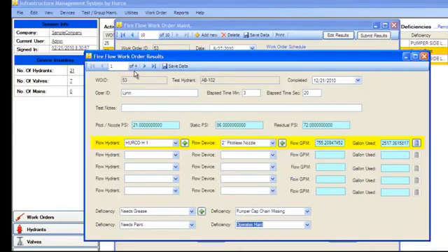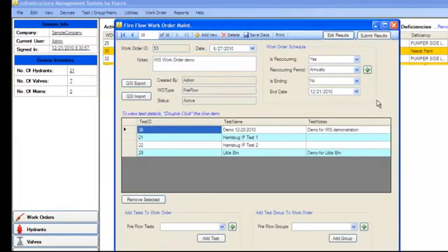And then I move on to the next hydrant, and the way I do that is to click on the little arrow, and now I'm on hydrant 2, and I can go in and enter that data as well. Again, if we had imported or synced with our FireFlow Pro system, all of this information would be filled in right now. So I'm not going to go ahead and do the other 4, but I'm going to come back.